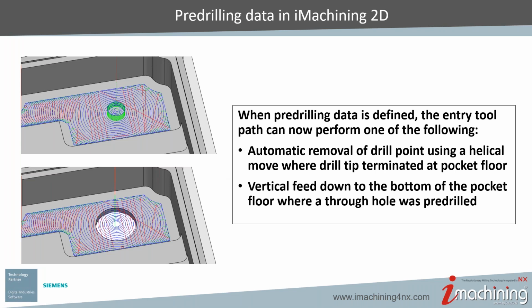They're using big core diameters, things that are really nice for iMachining style tool paths. But one of the things you lack is the ability to do helical entering, or there's just not a lot of cutting that you can do at the center. Technically they support helical entering, but it doesn't do a lot of good cutting at the center.